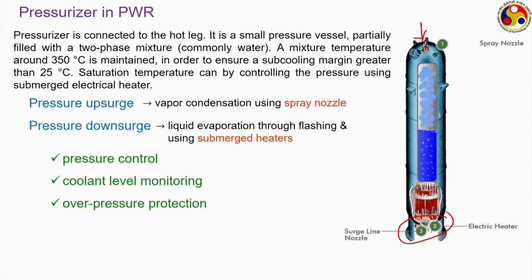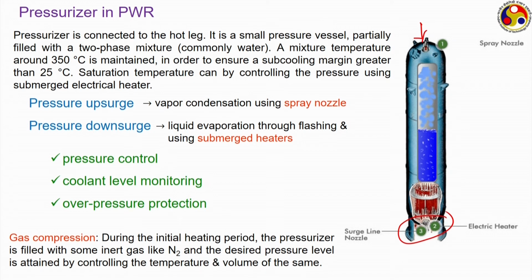Whenever there is some excess pressure which the pressurizer is not able to handle, then this overpressure valve will open, which is connected generally to a series of pipings, finally leading to the cold body of certain fluid, generally water, and from there it can come back to the pressurized water reactor again.